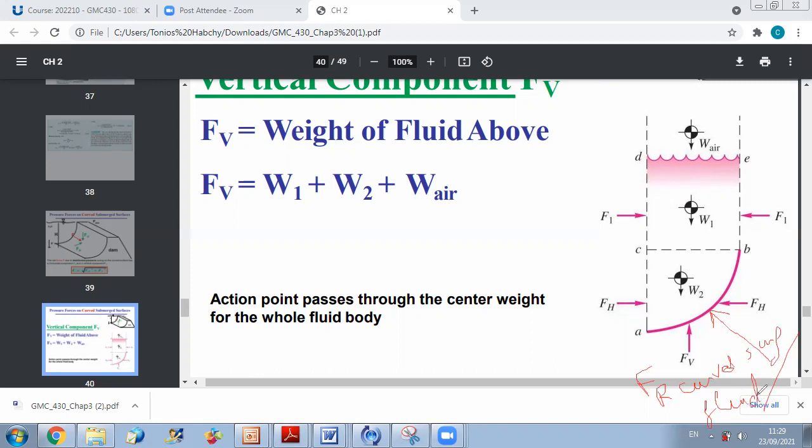once we find what are FH and FB, we will deduce the action of water on the surface by action reaction. So it will just be equal in magnitude, same direction, but opposite sides. Now, since I don't know exactly what is FR of the curved surface on the fluid, I don't know its direction, I can divide it into two components, one horizontal and one vertical.